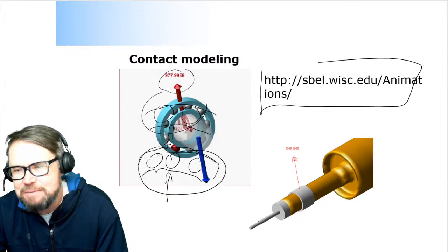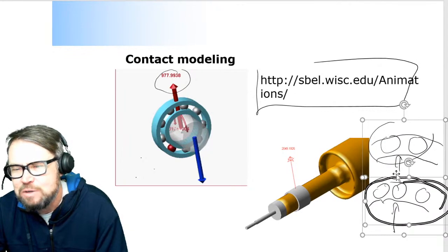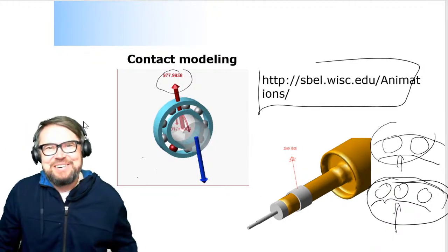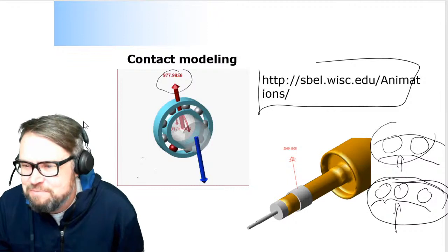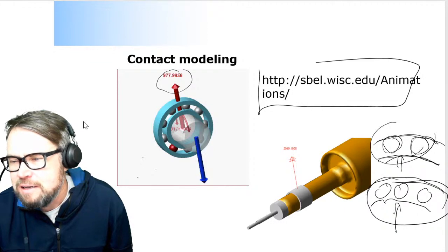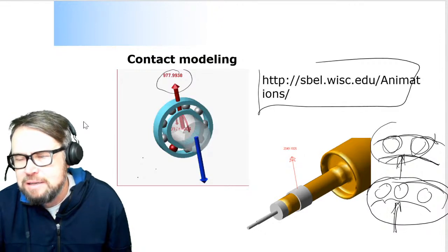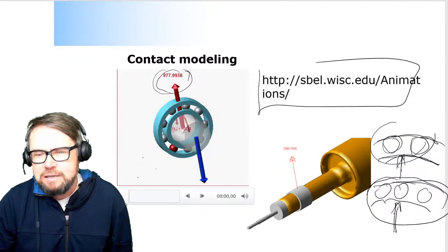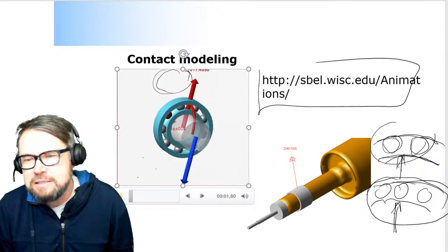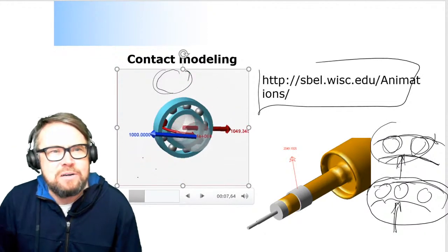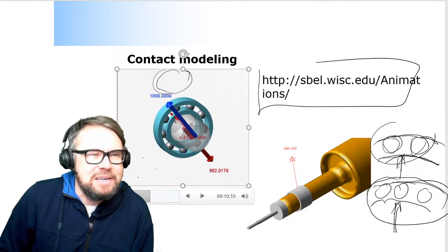There is of course a high temptation that I wanted to make a drawing in a place on the slide which is empty, and that's exactly where my head is located. Sorry. So I was about to tell that the support condition is different when the balls are like this and the force is traveling between the balls, or when the force is traveling through one ball. That's where the fluctuation is coming from. If you look carefully, the reaction force is not constant but fluctuating, and this fluctuation is because this boundary condition is changing.